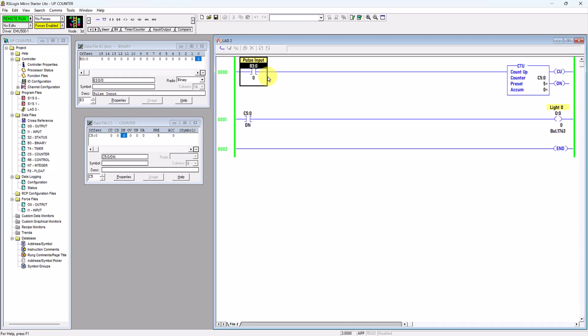So I will continuously generate the pulses to energize the up counter on and off until the accumulated value equals the preset value. This done bit will then automatically activate, and this will cause this virtual switch to trigger from normally open to close, and then you can see this virtual output coil will be energized.